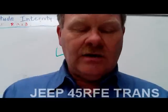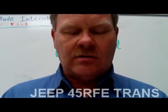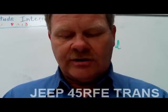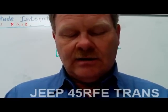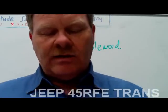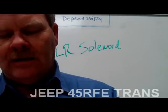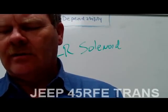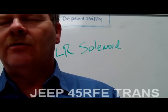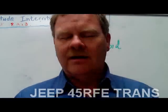And so you've got to look for diagnostic trouble codes, and since it's fully electronic, the diagnostic trouble codes are new for this particular model year we're talking about, which was like 2000 or 99. Okay, it's going to be slightly different. The MIL will be illuminated for some of them, and some of them will just have limp-in mode operation. Now that's been around for as long as there have been computers. A lot of times it's so you can come in from off the road. They don't want the computer to crap out and leave you dead in the water. So they've got what they call limp-in mode.